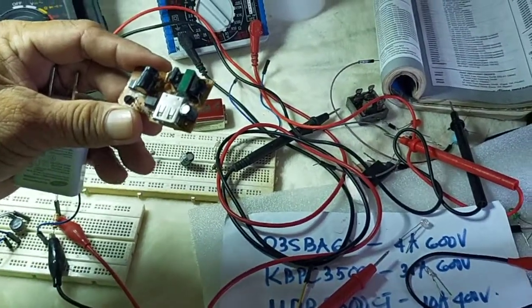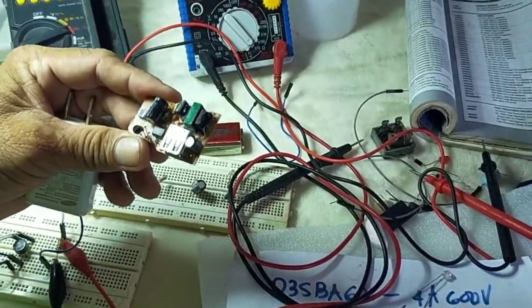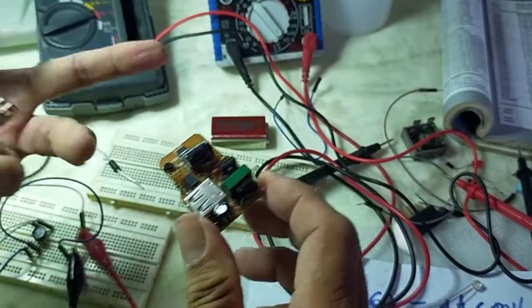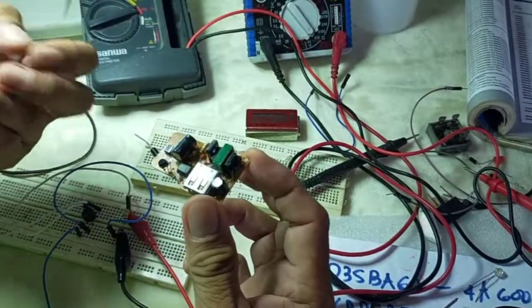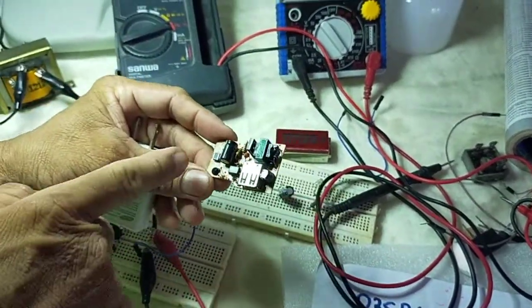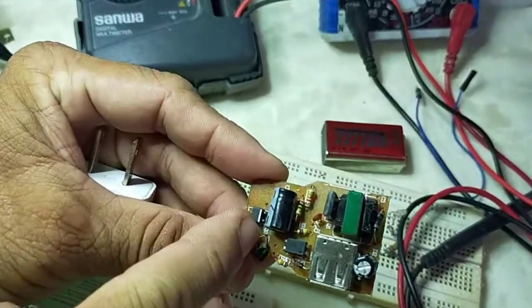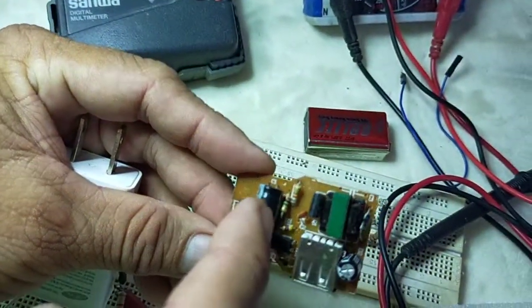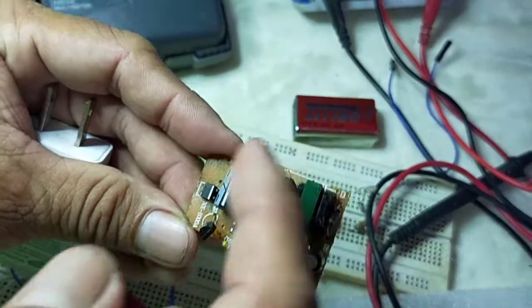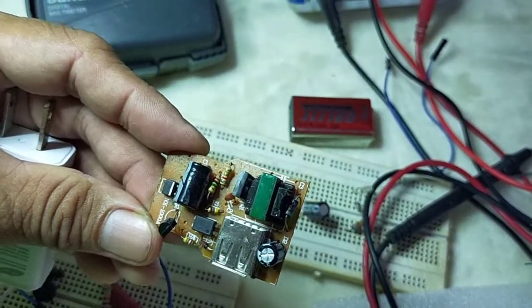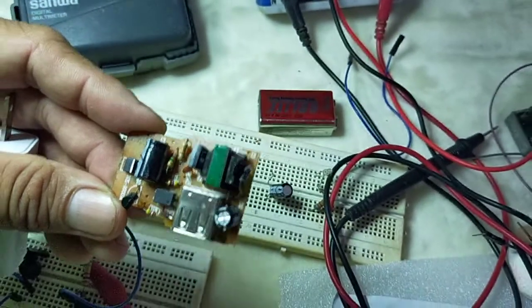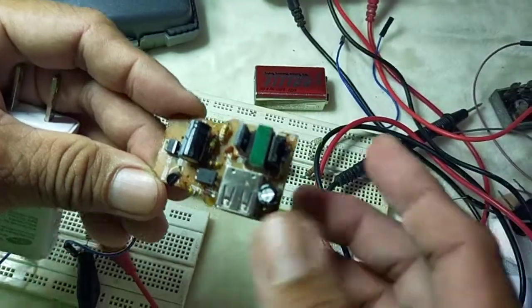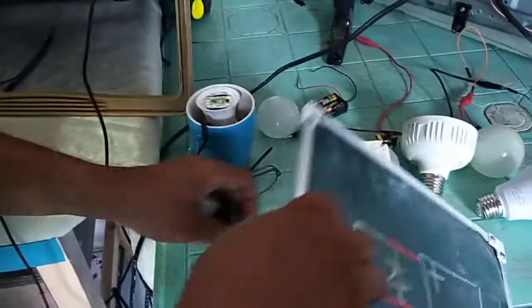When the battery is low, it should be charged, and this serves as a charger. It is actually a power supply, a rectifier circuit. The AC voltage here, 220 volts, is rectified into DC by means of this bridge rectifier, smoothed out by this supply filter capacitor. Then the voltage is lowered down into 5 volts DC, and it is regulated, which is needed by your cellular phone battery. Okay? Another bridge rectifier is here.